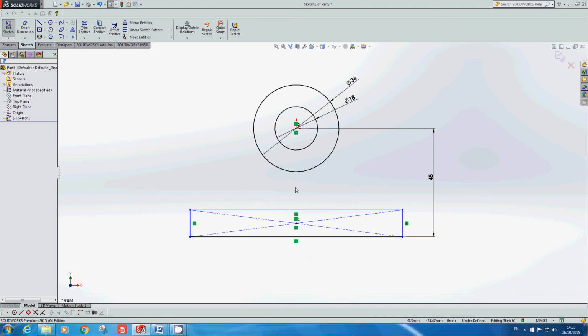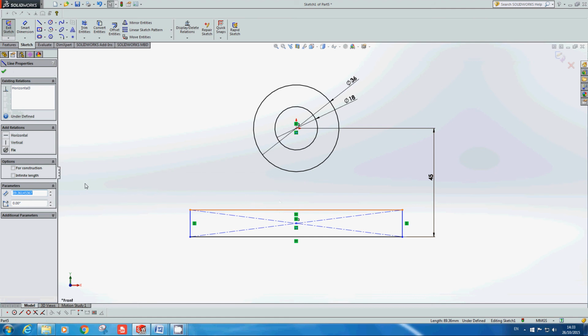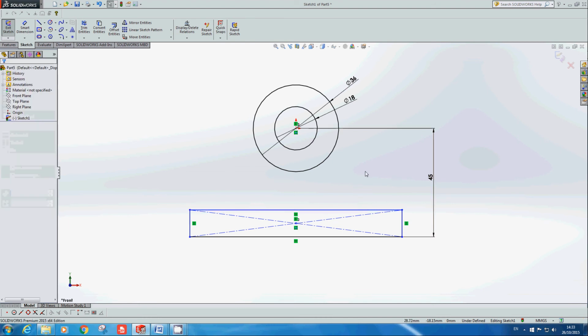And also, don't use the fixed constraint. It'll make your sketch fully defined, but it'll cause clashes and errors down the line if two instances clash.